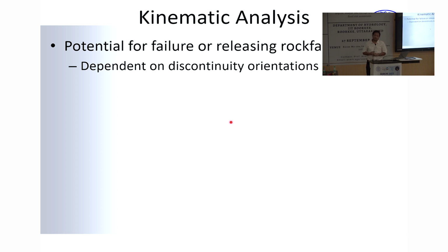And the third is the angle of internal friction. For most rocks, we have standard charts which give us the angle of internal friction. And the angle of internal friction can be understood in a way, for example, if you see a pile of rubble: gitti, morang, balu, three different materials.